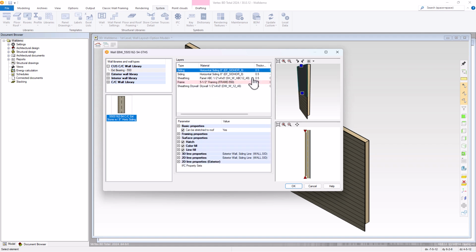Now that we have split the siding layer, the next step is to adjust the bottom height and top heights of the layers. Scroll the layer panel over to see the layer bottom and top height fields. Edit the bottom height field for the lowest siding layer. We will change this layer to the stone veneer.